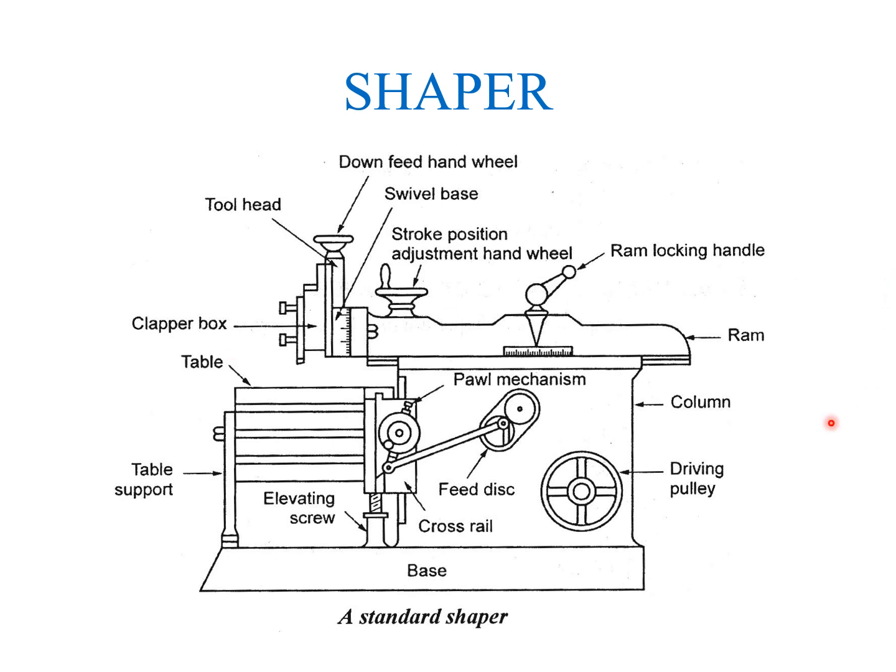Then column. The column is attached to the base. It provides the housing for the crank slider mechanism. The slideways are attached to the upper section of the column, which provide the path for ram motion. Then crossways. It consists of vertical and horizontal table slideways which allow the motion of the table. It is attached with some cross movement mechanism.